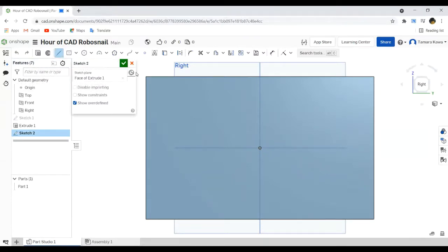And I want you to just sort of hover over this top line until it turns orange. Once it does that, you can click on it once, and you'll know that your line that you're creating right now is going to be coincident with that top line. You'll notice that there's going to be a dimension. I can do whatever angle I want. But you'll also notice when I start going down, you'll see this dashed line, and your mouse will sort of snap to creating a perpendicular line downward. So I want you to do that. Again, we'll change the dimensions afterwards.